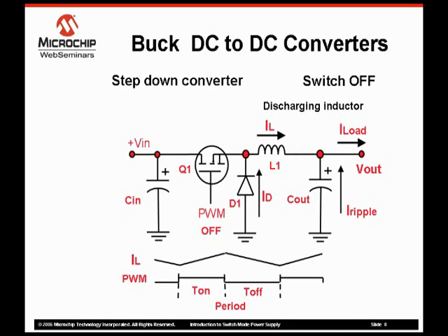The inductance value must be large enough for the given PWM frequency to ensure that the inductor current does not drop to zero before the start of the next PWM cycle. If the current was to drop to zero, then the control mode is called discontinuous. The discontinuous mode of operation can be more difficult to control than the continuous mode, where the current flow through the inductor is always greater than zero.